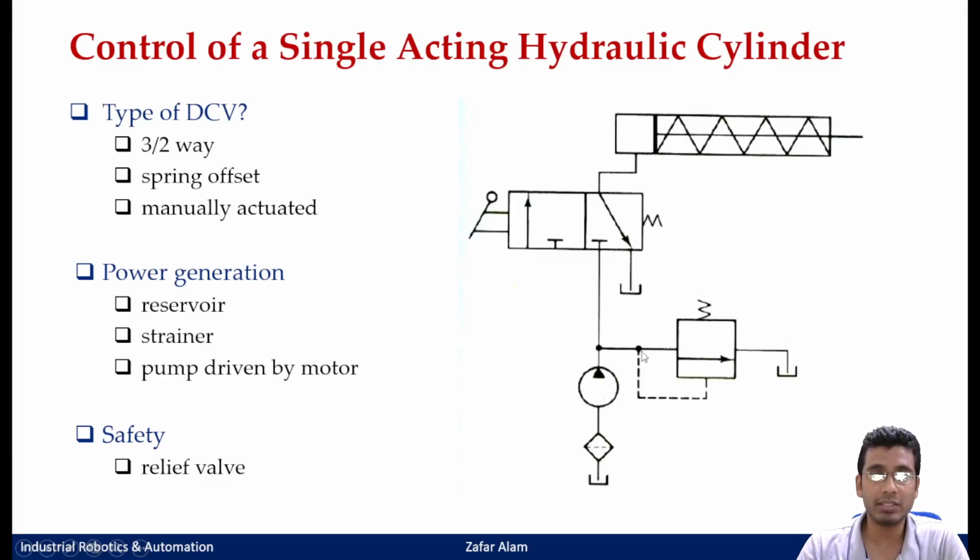So this relief valve would relieve the extra pressure by opening this valve and draining the liquid from your inlet to your outlet port. So this is a relief valve, and it protects the system against any exorbitant increase in the pressure. Whatever pressure you set, it would always make the pump run either below or up to that pressure. So this is a relief valve or a safety device that is put here.